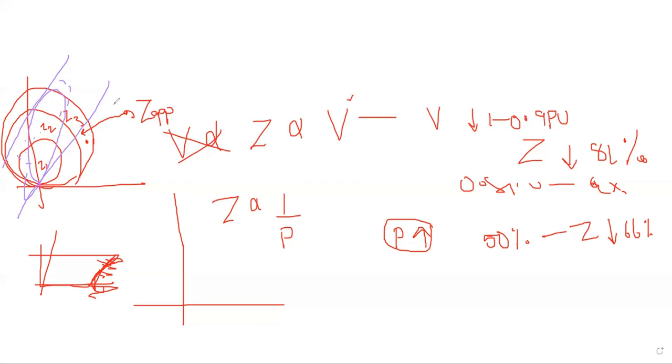But again, how to block this? Maybe this is coming. Actually, the fault is here. When I apply this blinder with respect to the apparent power, I am blocking this load region. But if a fault really occurs here, what to do? I have to block this load encroachment element. That can generally be done by checking the negative sequence overcurrent elements, or if my voltage drops during the fault, let's say a low voltage.